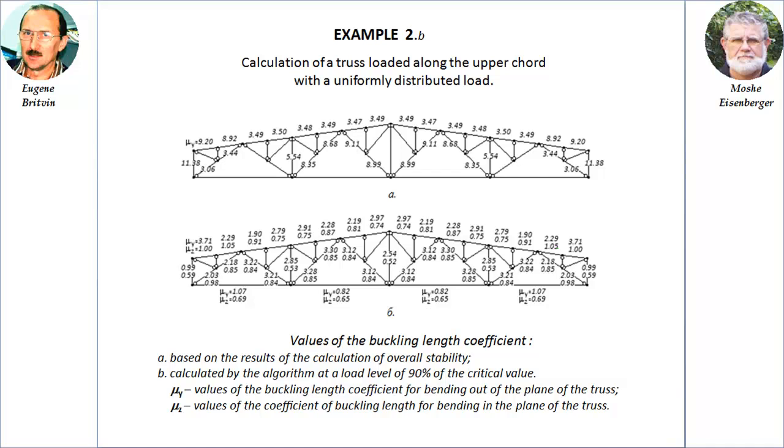Boundary conditions are determined by the structure and its stress state. The higher the stress state of the structure, the more weakened the boundary conditions for a particular member, leading to a lower critical parameter alpha and, consequently, to higher buckling lengths. Therefore, kilometer-long buckling lengths are obtained when we intentionally reduce the structural resistance by proportionally increasing the forces in all elements when calculating the overall stability. In order for the buckling lengths to correspond to the actual boundary conditions of the rod, it is necessary to include the actual stress state in their analysis, which is ensured by the algorithm described above.